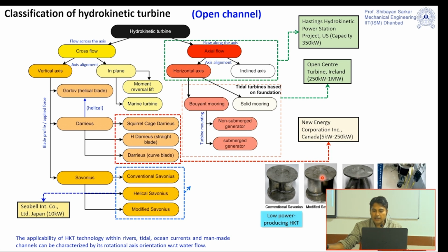Now there is another one, the modified Savonius turbine. In this modified Savonius turbine, if you remember, last day I talked about the overlapping ratio. Overlapping ratio means two S shapes were there. In the normal condition, there will be a shaft here, one blade here, another blade here. Now in this particular design there will not be any shaft; rather, one blade is there, another blade is there, with an overlap part. So instead of a shaft, this turbine is held through the top and bottom plates.